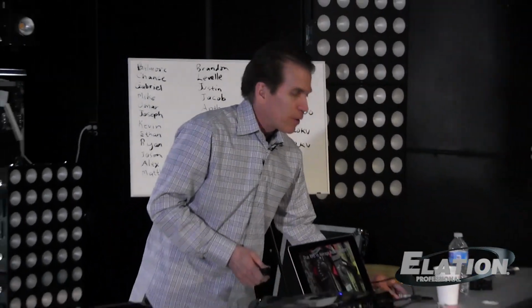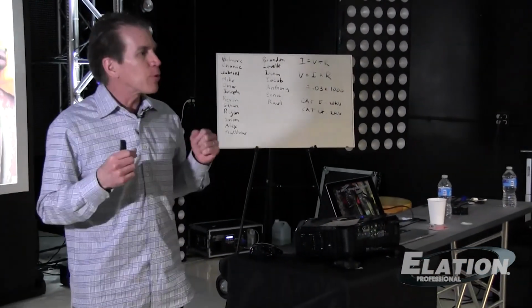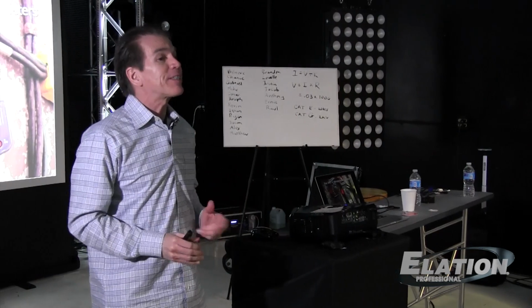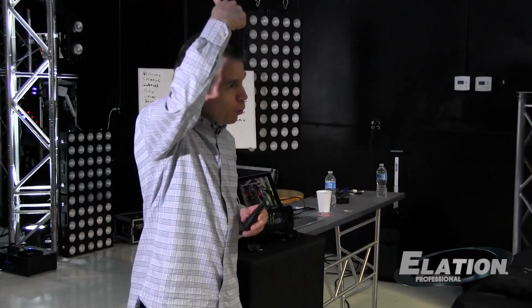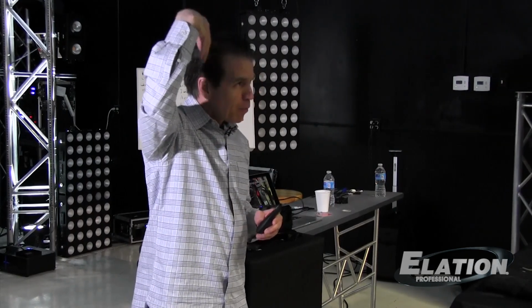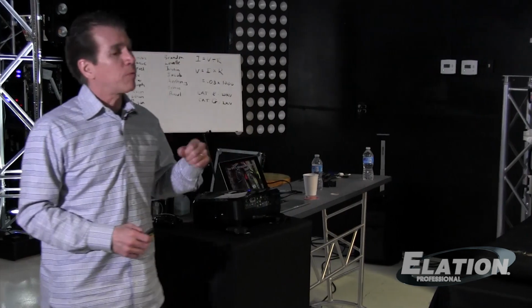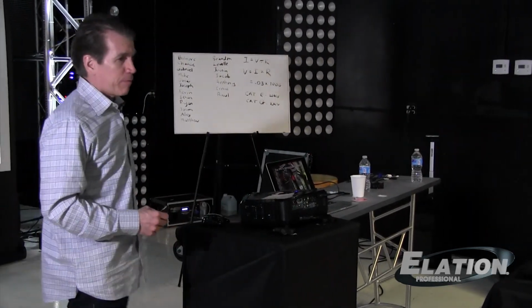Now, the climbing helmets, the Petzl climbing helmets are great for riggers. They're vented, but not so good for electricians. The reason is that if there's an arc flash, it gets really hot really fast, and those holes in your head gear can let heat burn your scalp. So you need to make sure you have the right one. Petzl makes headgear that's rated E, and they have them that are rated G. So make sure that if you go out and get that stuff, you get the right stuff.